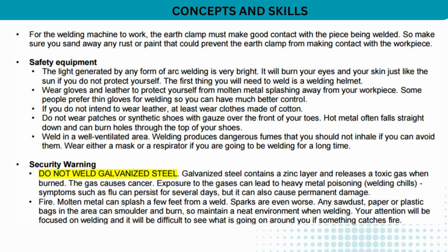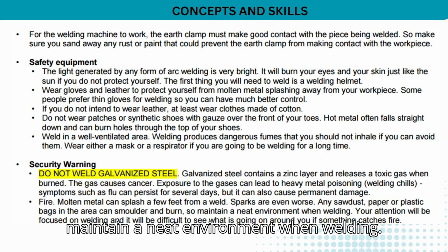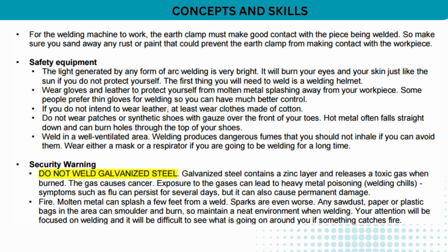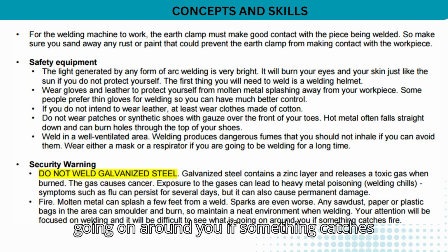Fire. Molten metal can splash a few feet from a weld. Sparks are even worse. Any sawdust, paper or plastic bags in the area can smolder and burn, so maintain a neat environment when welding. Your attention will be focused on welding and it will be difficult to see what is going on around you if something catches fire.